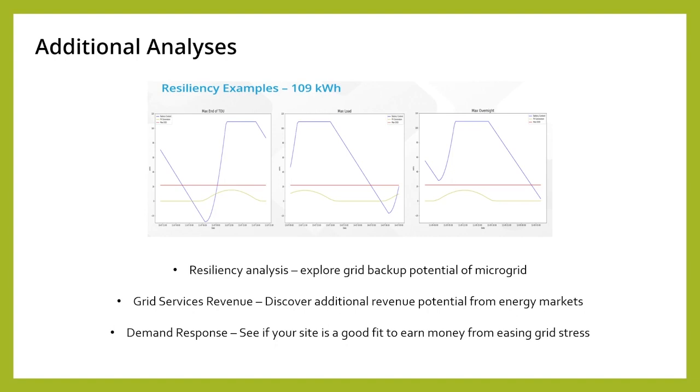We've been talking a lot about time of use, resilience, and peak shaving, but there's other things to consider here too. There's revenue available for grid services, utility, or other programs where you can charge and discharge your battery to help the grid, get paid some additional money. Another flavor of this is demand response, right? If the grid is under a lot of strain, you can discharge your battery, help the grid stay stable, and again, get some payment. So all of these things together, all these different applications together, we should consider them all, and the best system will again fall out of the analysis, given a kind of conversation with your customer.